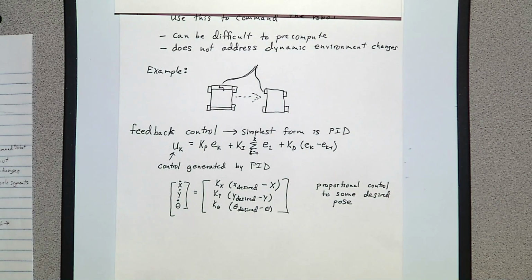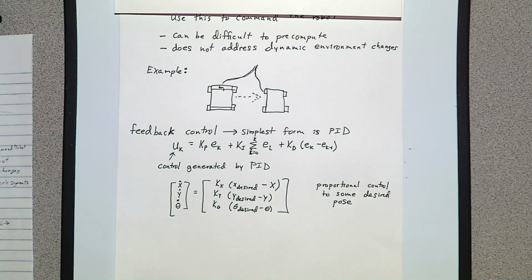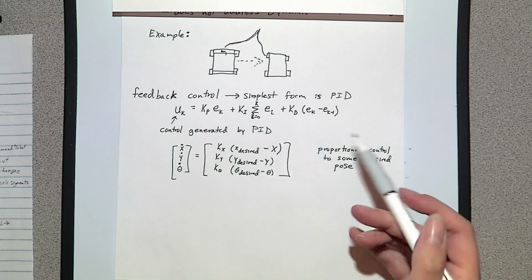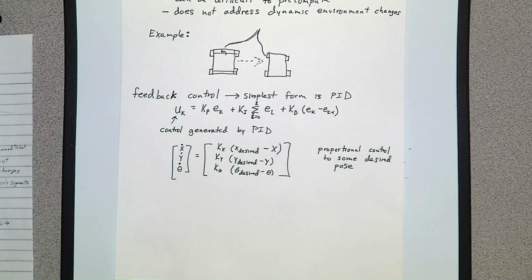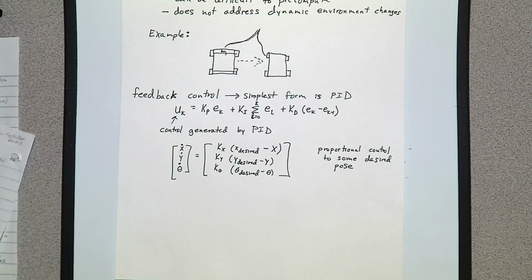So, of course, the big question is, how do you actually get this x, y, theta? In a few classes, we'll be talking about ways that you can localize your robot, so figure out where your relative position is to some fixed point. Typically we use a lot of sensors to achieve this, because our odometry can only get us so far because of things that we talked about before, like the slippage of the wheels, changes in the environment, and so on.